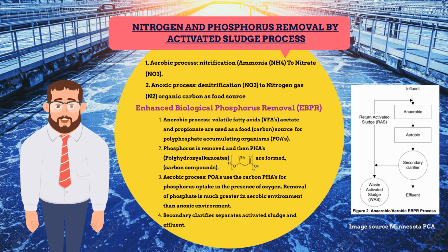The activated sludge process can also be modified for nitrogen removal, to encourage nitrification followed by denitrification. By modifying the biochemical oxygen demand load, mixed liquor suspended solids, and retention time, a nitrifying population of microorganisms can be established. The growth rate of nitrifying bacteria must be higher than the growth rate of heterotrophs. Hence, nitrification is expected at a sludge age greater than 4 days, and denitrification must follow nitrification in order to remove nitrogen from the wastewater.